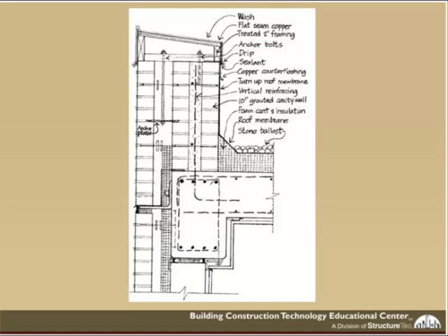Okay, next we're just going to look at some examples. Like I said, the flashing systems. We're looking here at how some of the penetrations have been flashed, or the openings have been flashed. Specifically, we're looking at the importance of end dams on that right-hand picture. You want to make sure that the flashing is terminated properly, or else water will continue to travel horizontally, never get captured and sent out of the system. If it's not end dammed properly, the moisture will find its way into the interior of the facility.